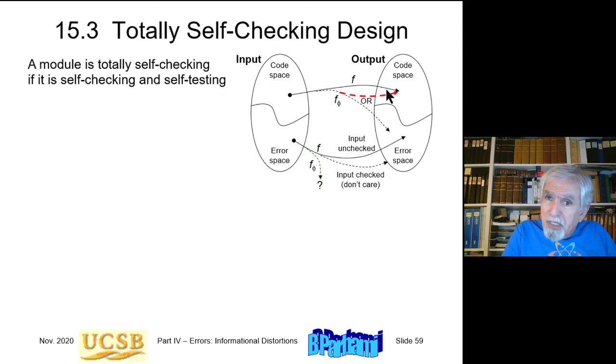Now, if the circuit makes too many of these corrections, so there is a single stuck-at fault, but that single stuck-at fault does not affect the output because I've designed the circuit to be fault tolerant, then at some later time, a second fault can develop in the circuit. And now the circuit is not tolerant of two faults, so I run into trouble.